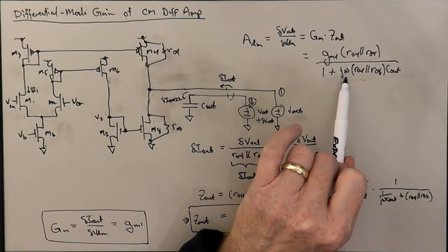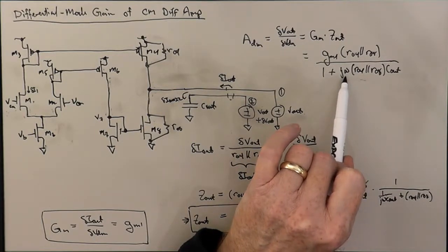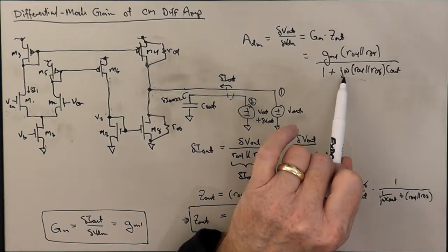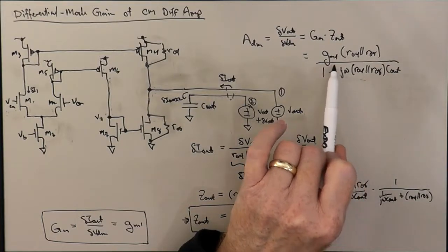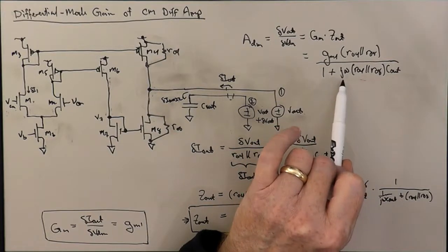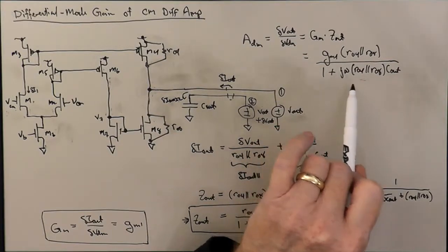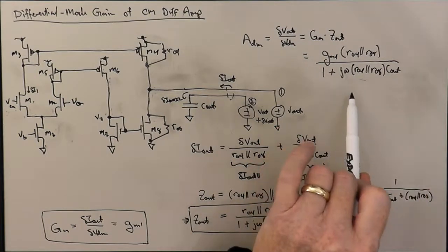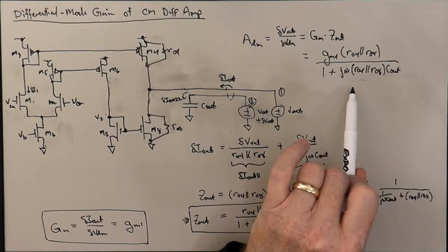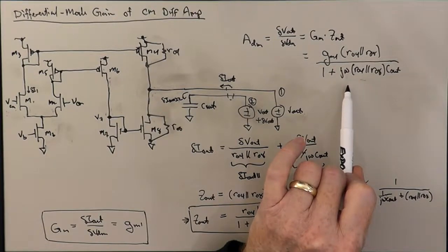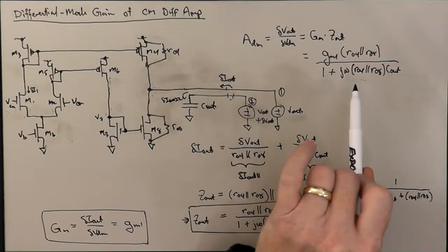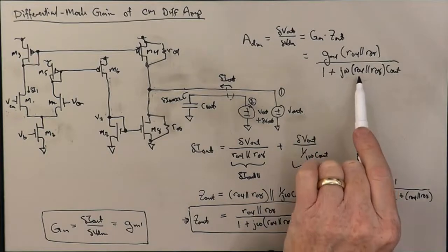And so it's basically kind of got a low-pass type characteristic. So at low frequencies, the gain is high. It's about on the order of 100 or several hundred or something like that. And then it kind of has this pole, this normal pole, 1 over 1 plus j omega tau, that hopefully you'll remember from your ISIM days. And the roll-off is 20 dBs per decade